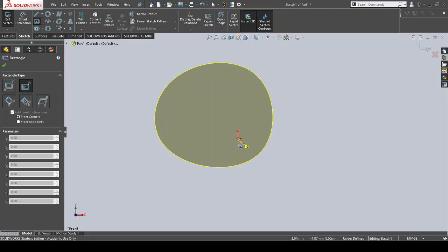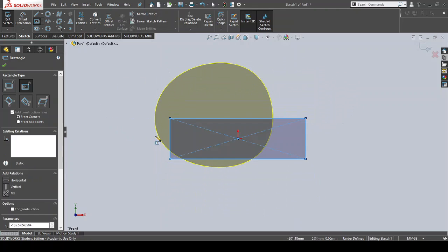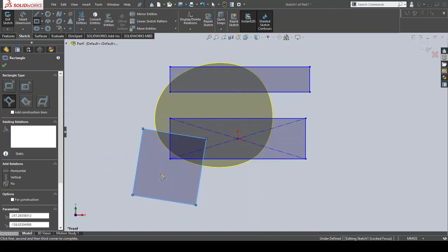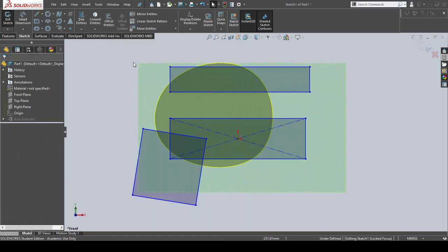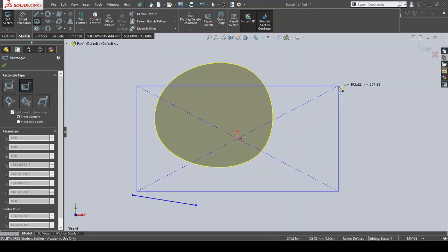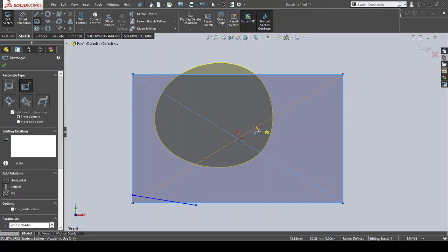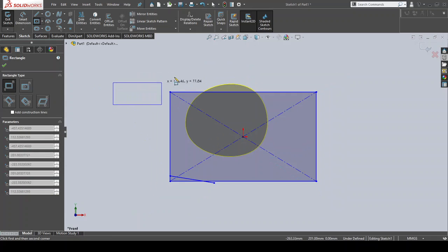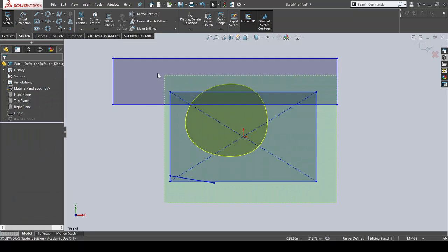A rectangle, here we go. And that's one way of drawing a rectangle. Here's another way, and then you can go through each of them. If you do need help, the numbers tell you which point you're starting off with. For example, this one is called the center rectangle because the first point you're selecting is the center. And then the second point is one edge of the rectangle. And then here we have an edge rectangle, where we're selecting one edge and then a different edge.